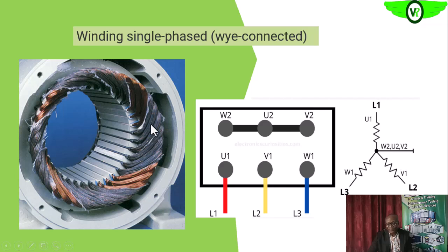Okay, so if that single phasing is sustained for some time, remember there may be load on the electric motor too, you will see the burning of those 2 sets of windings, while one is intact, the one that has the open phase. So if you see this, it is a signature of single phasing on the electric motor.